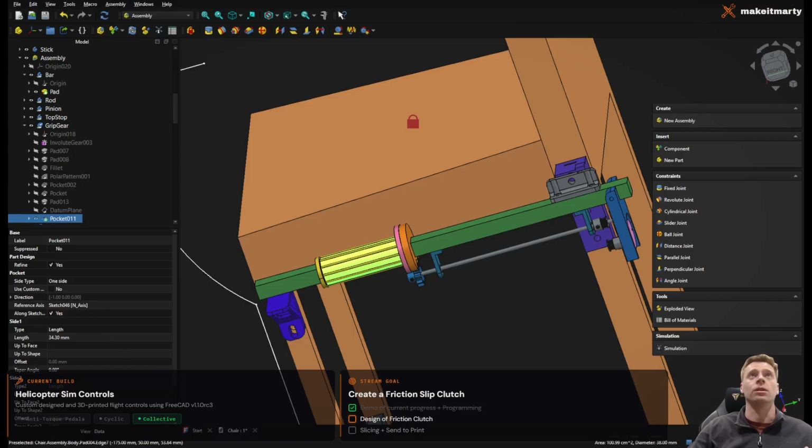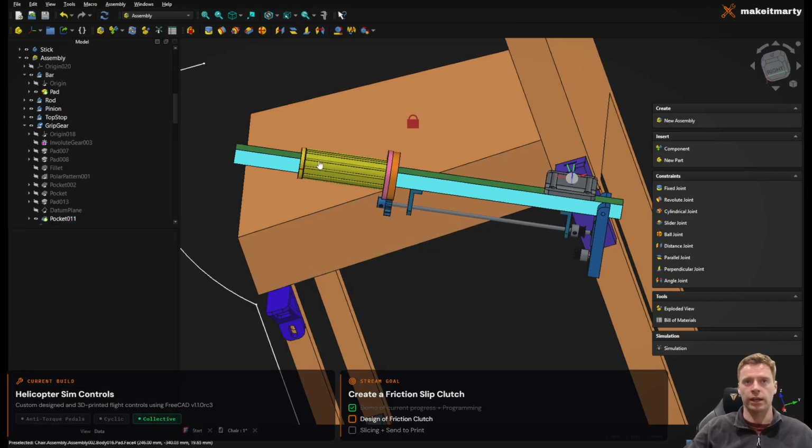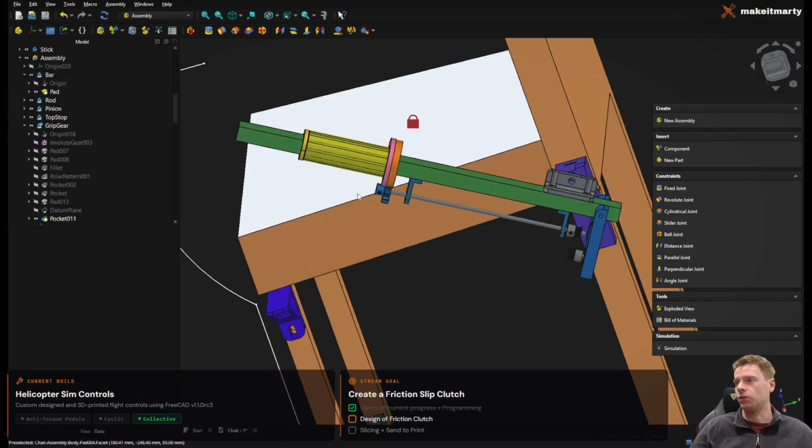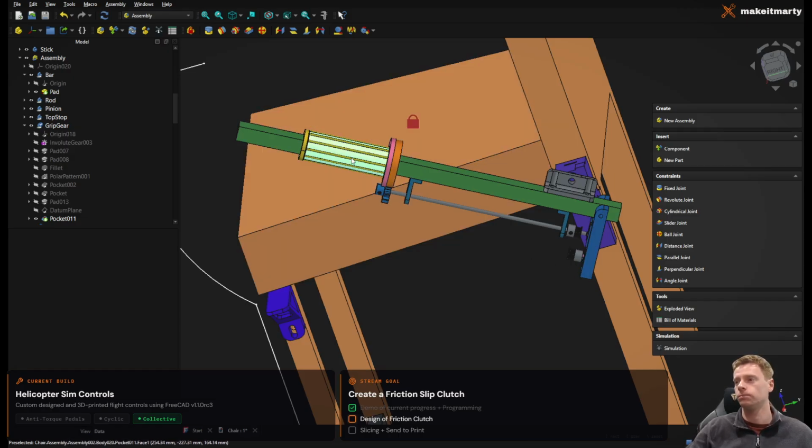So the ideal thing on, let's say, a G2 is 530 RPM. So if you were to raise the collective like that, that's obviously going to require more energy and require more throttle. So what the governor will do in that circumstance is it will put in more throttle.